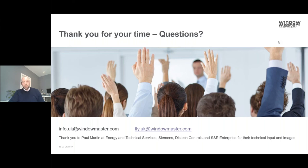Our buildings now, new buildings, are so well insulated and typically fairly densely occupied that potentially you could have no heating demand down to outdoor temperatures of 5 degrees or even less. So we can address overheating issues as well in winter. But normally CO2 control in winter is predominant, and it's temperature control in mid-seasons and summer. That would be the focus.